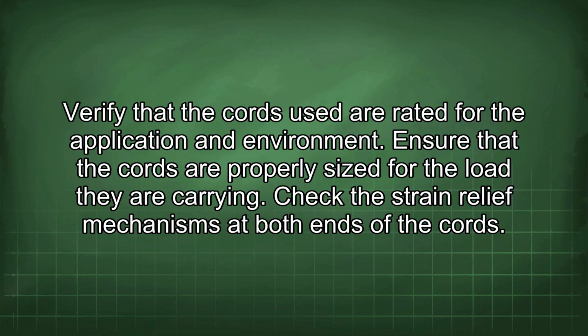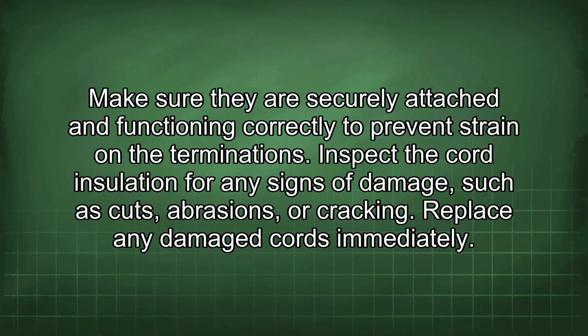Check the strain relief mechanisms at both ends of the cords. Make sure they are securely attached and functioning correctly to prevent strain on the terminations. Inspect the cord insulation for any signs of damage, such as cuts, abrasions, or cracking. Replace any damaged cords immediately.